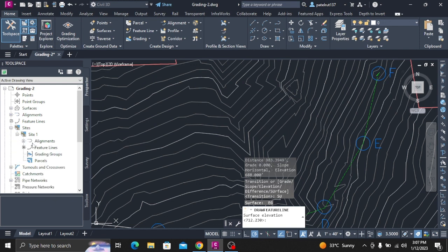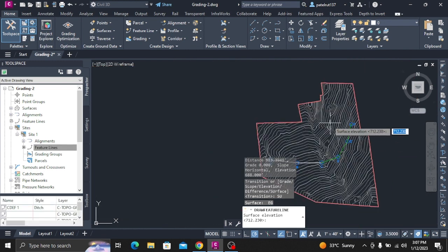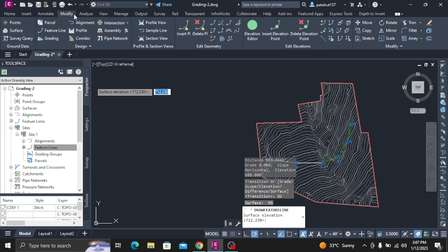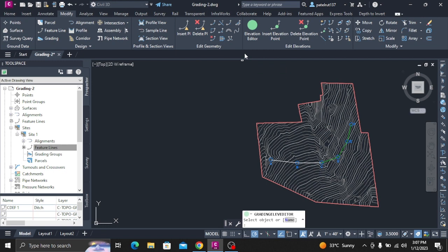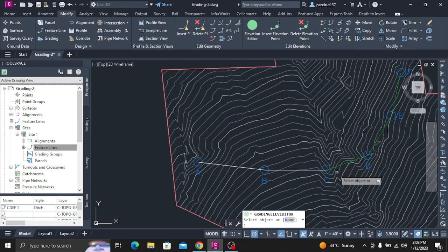In the Grading Creation Tools toolbar, click Select a criteria set. Select Ditch criteria set from the list. Click OK. In the Select a Grading Criteria list, ensure that Distance at -6% is selected. Click to expand the Grading Creation Tools toolbar. In the Style list, select Ditch. Create gradings. Click Create Grading.